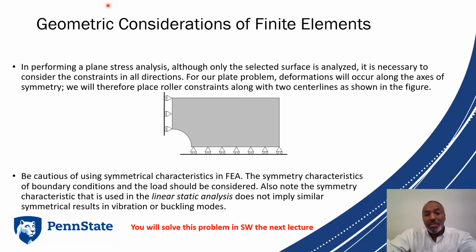A couple of things to consider. Be sure that when you are looking at the symmetry of the geometry, you also have symmetry of the loading. Like I said, this one's loaded on the left and on the right, and it's normal to the surfaces, so everything's good there. Also, symmetry may not apply to responses in a dynamic analysis or a buckling analysis the way it does in a linear analysis. So in this standard static linear analysis, we know what the deformed shape is going to look like. We know it's going to be symmetric with respect to these horizontal and vertical planes, such that we can apply these without a lot of problem or issue.